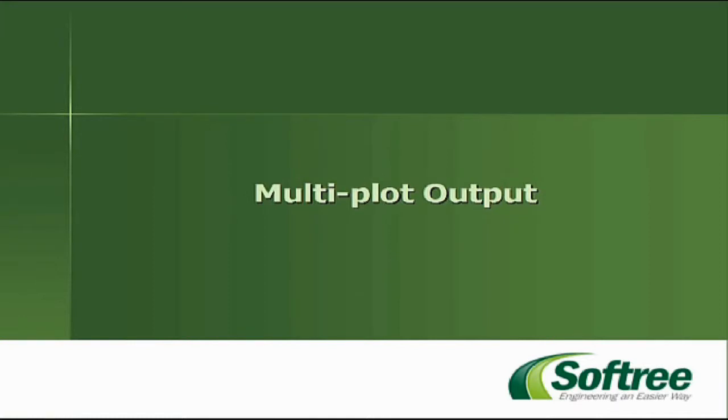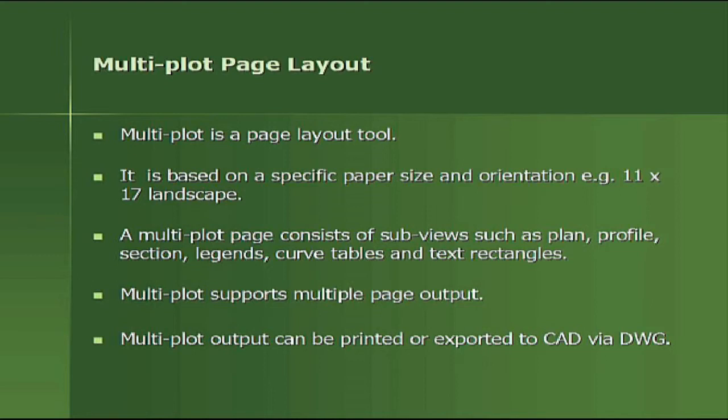Multiplot output. Multiplot is a page layout tool. It is based on specific paper size and orientation, example 11 by 17 landscape. A multiplot page consists of subviews such as plan, profile, section, legends, curve tables, and text triangles.